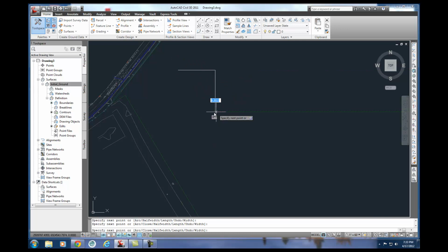If I draw it just like this, and let me just close that, this is my polyline. If you look, when I click on one of the segments, they are each connected to the other. The end point of this one is the beginning point of this one and all that. That's a polyline. Now, like I said, Civil 3D likes polylines.